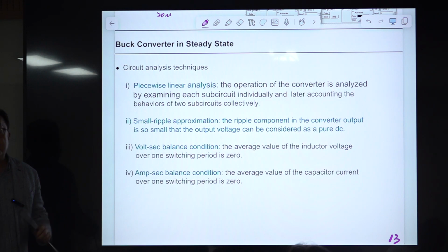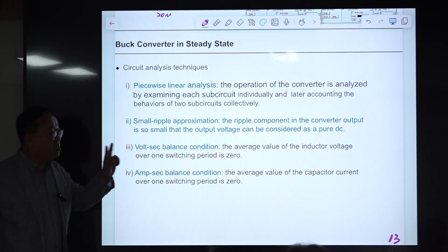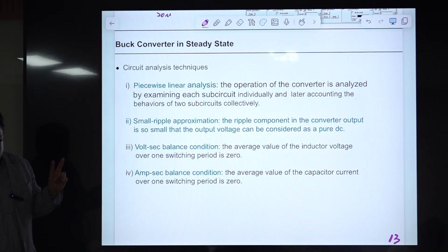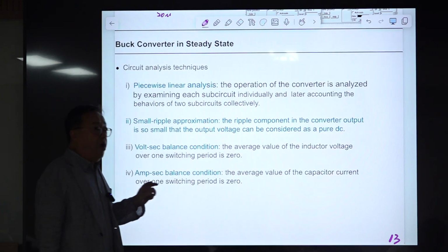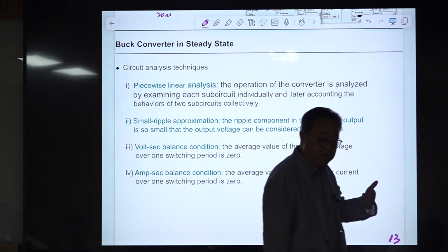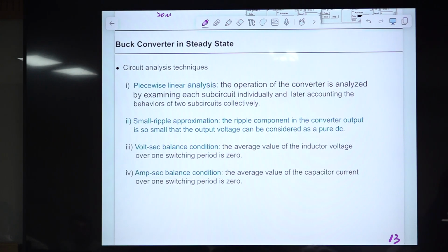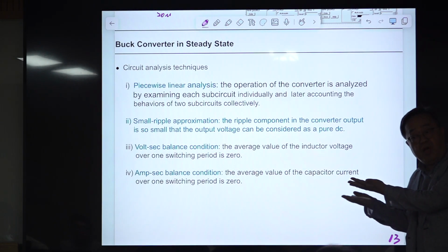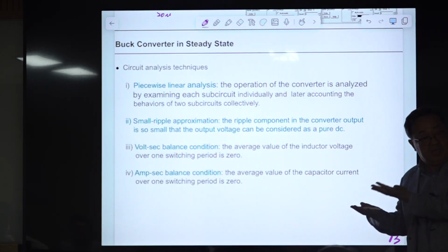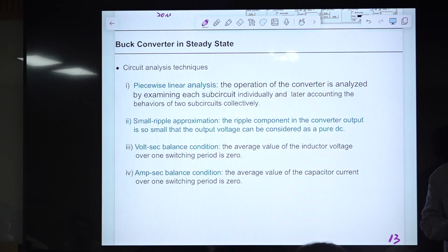The justification for this is that there are 2 aspects. One is everyone is trying to reduce the ripple component. So they are using large capacitors to reduce ripple. They use a 2-stage output filter to reduce ripple. So ripple, for practical applications, is so small it can be ignored. The impact of ripple on the circuit operation is nearly negligible.